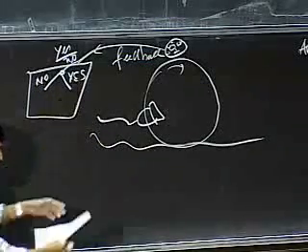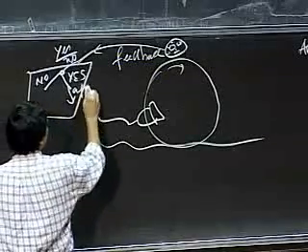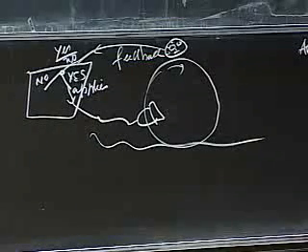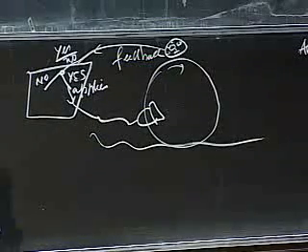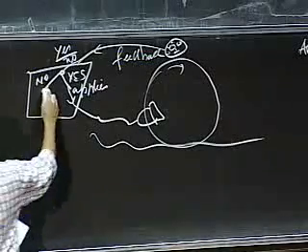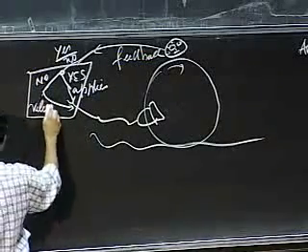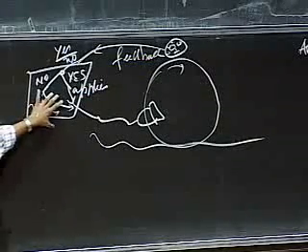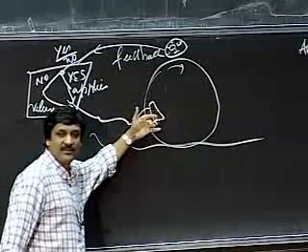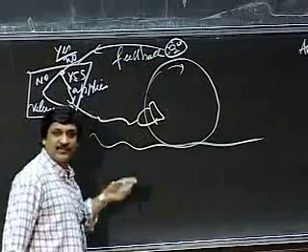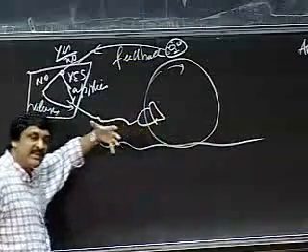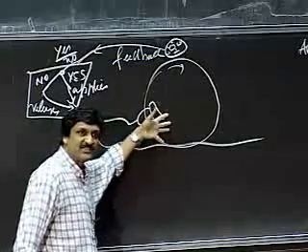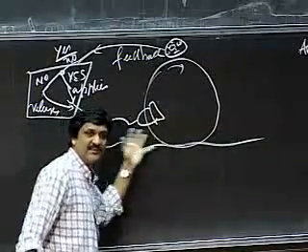If it's yes, then the controller applies the brakes even more strongly. It's turning, so I can apply more brakes. But if it says, oops, it stopped turning, the controller simply releases the brakes. As soon as the controller releases the brakes, the tire loosens up a little bit and starts turning again. So this way you're constantly keeping the tire in its region of critical friction so that it's constantly moving, and static friction applies to how hard you can brake. And it doesn't start skidding.